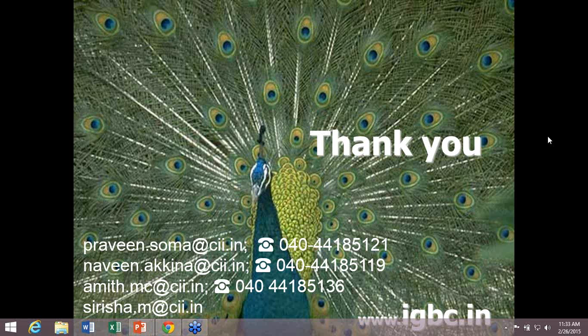There is a query from Yusuf Turab. If soil test is not available, is there a worst case scenario thumb rule we can use to show rainwater harvesting capacity? In the earlier questionnaire, I told you that you can consider a percolation rate of 1 cubic meter per hour for the calculation purpose only, to show the rainwater harvesting correctly, and also arrive at your rainwater harvesting capacities for your project.